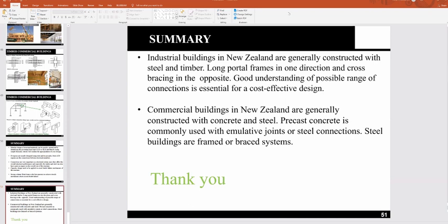For high-rise structures, we use high-grade materials, which are usually brittle. How can we overcome its brittle nature with ductility? Now your concrete is brittle, I understand. Your concrete strain can be increased by providing active confinement. You can't see concrete as simple plain concrete. You need to provide active confinement so that even if spalling happens outside your cover zone, your member within the confinement zone is intact.